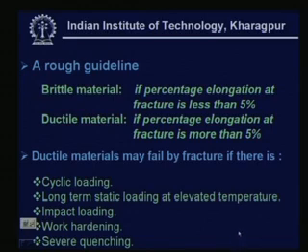That means continuously, if you consider a material member, suppose this way, and you just bend it like that, again you bend it on the other side, bend again in the reverse direction. So, what is happening? Suppose at the top fiber if we consider, then continuously in one cycle it is undergoing a tension, and in the next cycle what is it undergoing? It is undergoing a compression. So, that is what we understand by a cyclic loading.